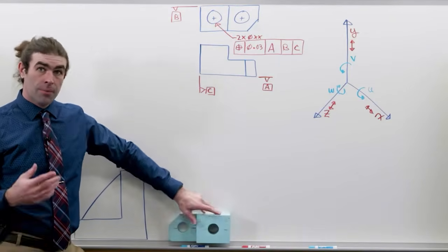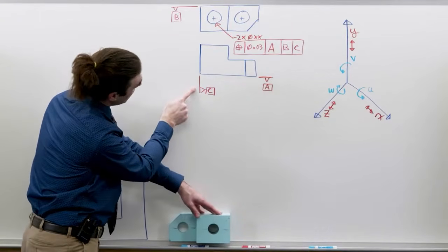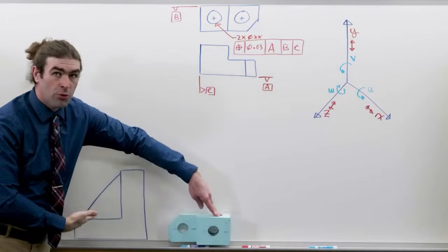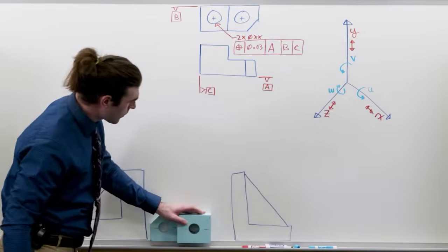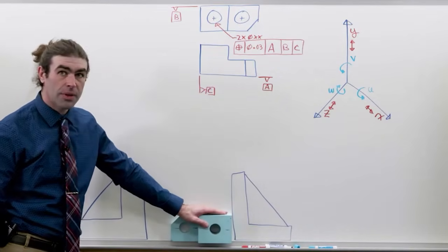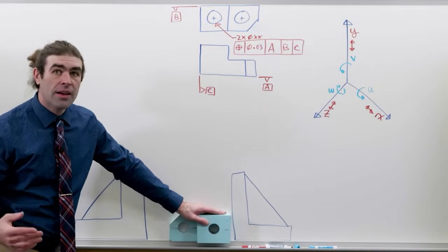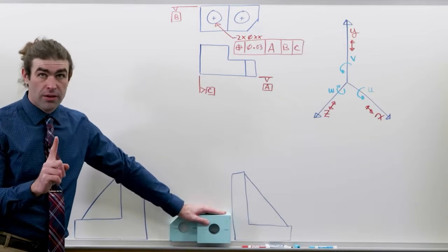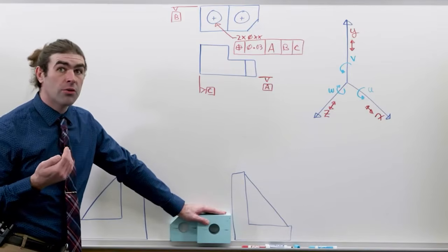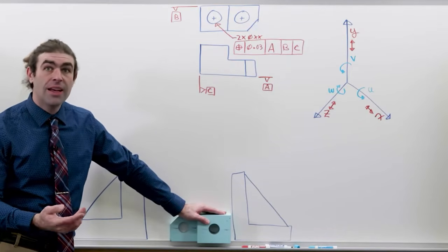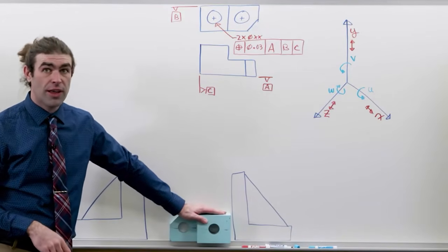Okay? The last is datum C, which is going to be this side right here. And I actually drew my angle plate on the wrong side, so let me draw it again. So we're going to push it up against something. On an open inspection, a lot of times it'll be something like an angle plate. Now, it only needs to make 1 point of contact with the angle plate. The reason being, it's only controlling 1 degree of freedom, just the translation. To stop it from moving left and right, you only need 1 point to achieve that.